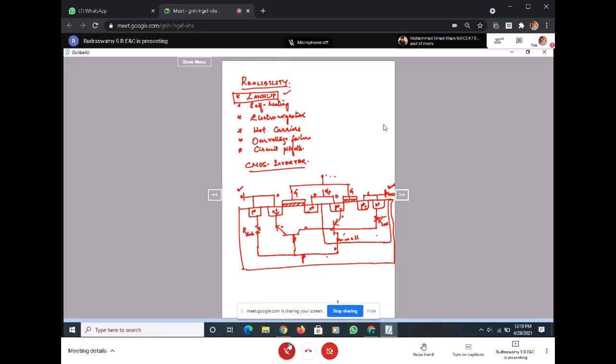Now what I'll try to do is write this particular circuit in another way. I'll ensure that my VDD is at the top, and at the bottom I have the VSS. Whatever cross-section you are seeing, this horizontal version I am writing in vertical form. So VDD, which is on the right, I am pushing to the top, and VSS or the ground, which is at the left, I am pushing to the bottom. I'm just doing a 90-degree shift left.